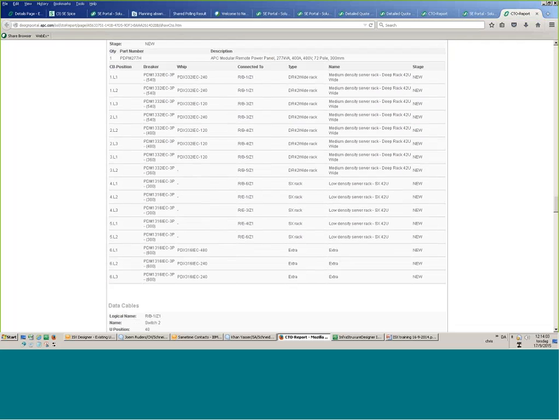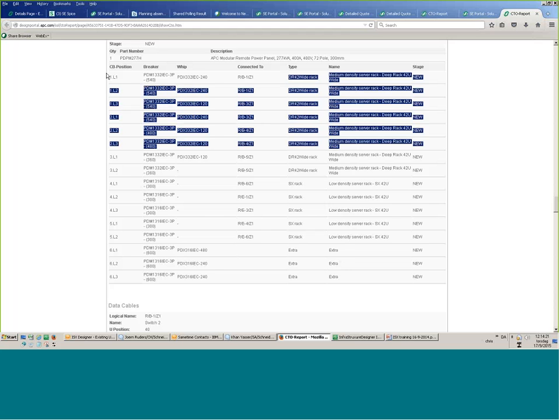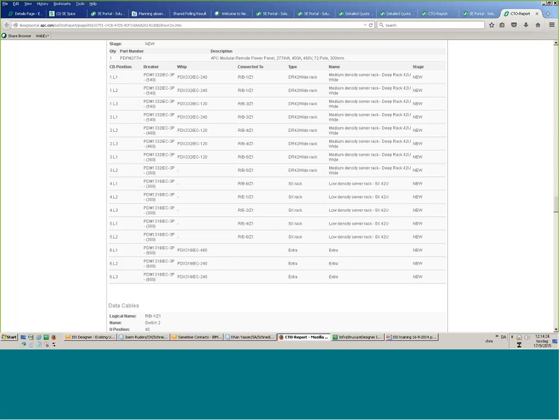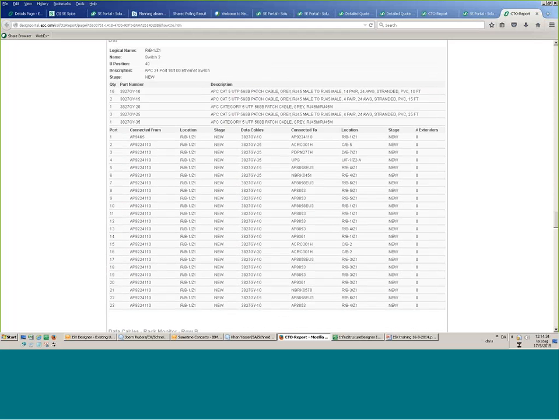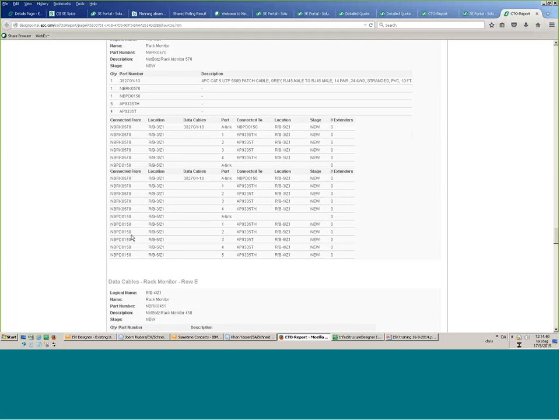So there is an option, so it's not something you have to use, where one Rackman PDU here is on phase 1, and the second Rackman PDU will be on phase 1 of the next model. That if one model breaks, I still have phase, and also for balancing, if this one Rackman PDU goes, then I still have the load on L1. So this is an option which has been requested from some countries. So this comes. Then I have here the Cat5 cable calculation and the placement of all my ports.